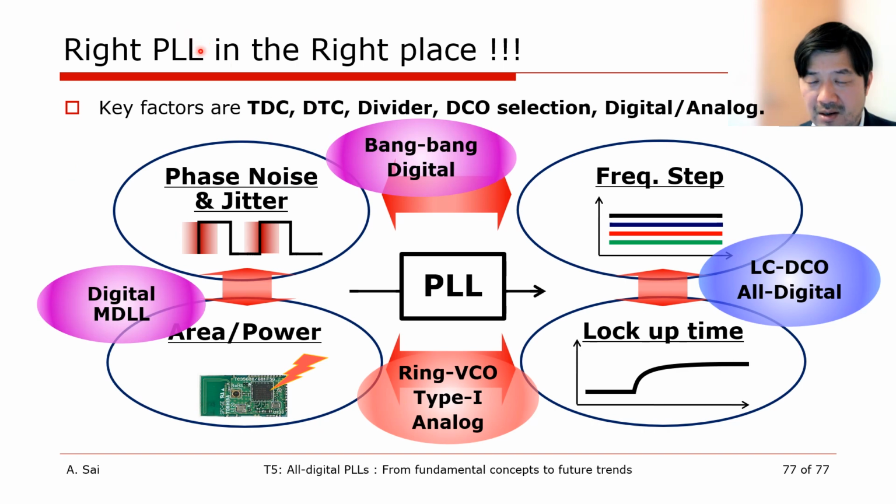Finally, my message is: write PLL in the right place. In some cases, analog PLL using a type 1 loop and a ring oscillator may be the optimal solution. Very, very simple design. I think this is a great attraction of integrated circuit design.